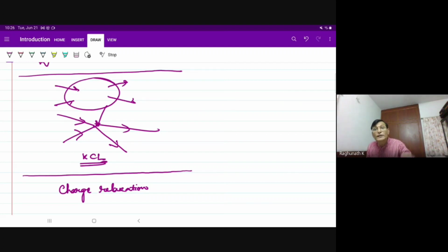And this charge relaxation and relaxation time, you should know, among so many theories, is used to explain something called the Gunn effect, where you apply just a DC voltage and you get a pulsating current. It is actually a microwave source, the Gunn diode. When you apply a DC voltage, you normally expect the current to be DC. But the Gunn diode is a device which produces pulsating current for a DC applied voltage.